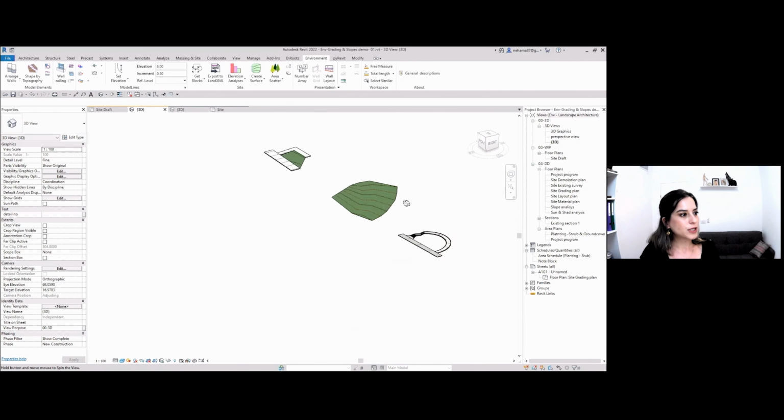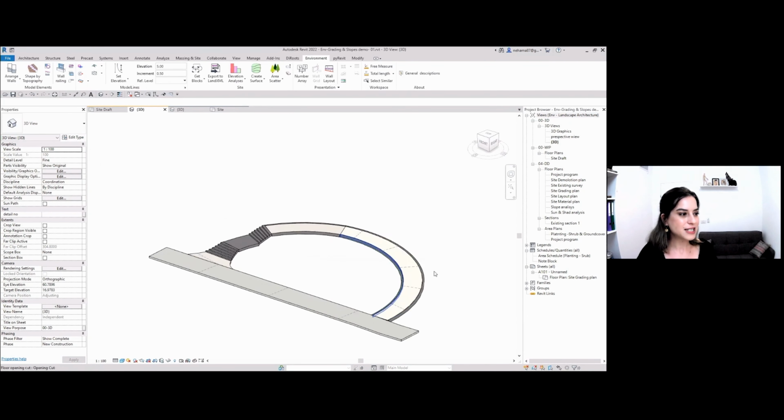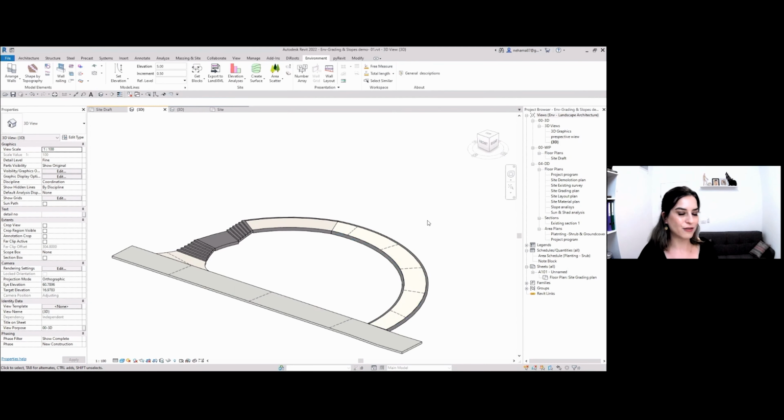So we saw these really nice 2 examples of creating a topo surface from model edges. And then we saw how to create a topo surface from model lines. But what if we want to create a topo surface from model lines that are snapping to model edges? Well, you're correct. We go again to Environment tab. This is actually one of our newest features, and again, another personal favorite. It's called Snap Work Plane. And to understand that, it's better to see what it's doing.